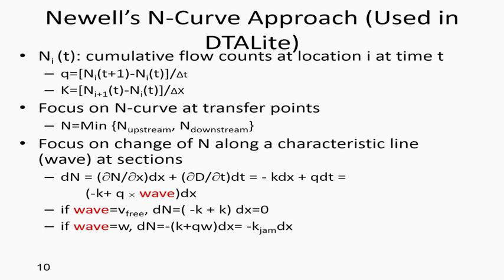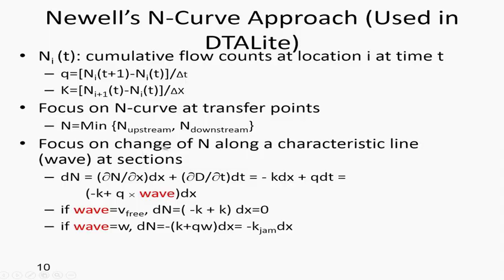Basically, we simulate a number of agents throughout this intersection, and we can always count the incoming flow cumulatively, the outgoing flow cumulatively, and then we can draw the corresponding cumulative arrival and departure curves, and then calculate the corresponding flow rate and the density as the number of vehicles or number of agents in the system. And if we try to calculate how many vehicles are transferred between those transfer points, then we can use those N-curve propagations to do the calculation.